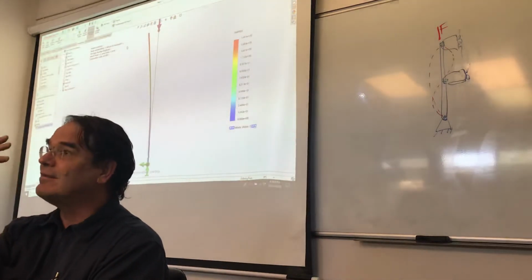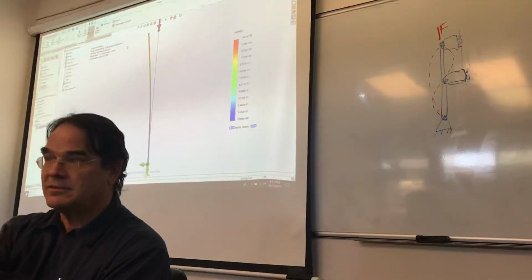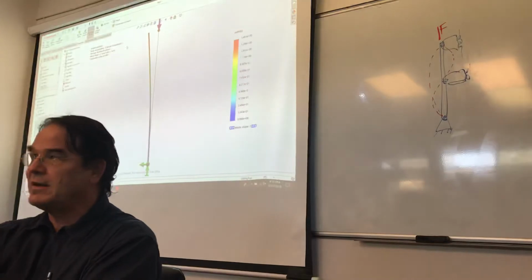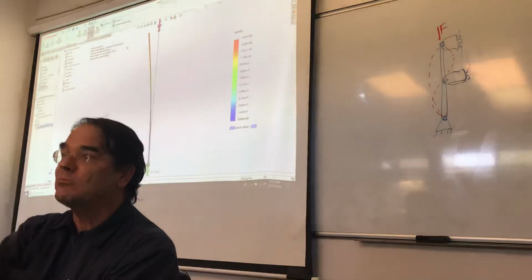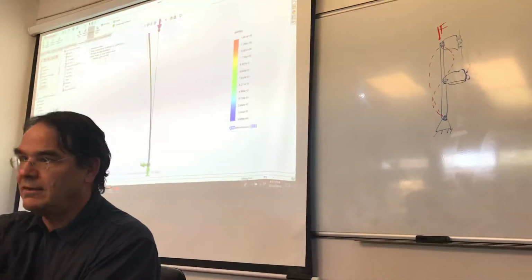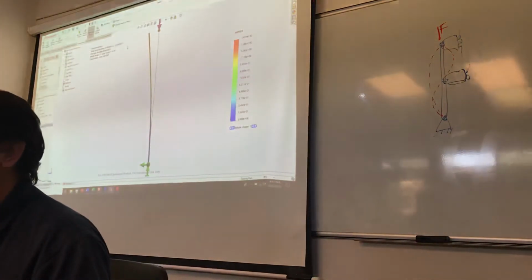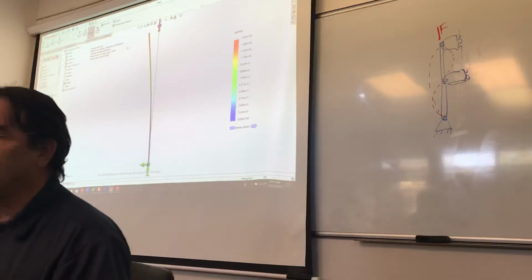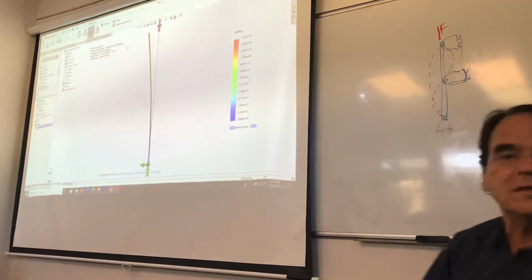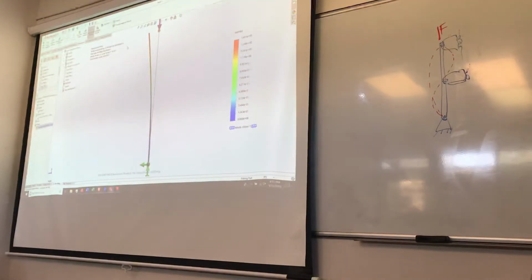But it takes a lot more to fail in one direction than the other. So it's buckling in the skinny direction at 11,000 pounds, or predicting that, and it's buckling in the wider direction at the 30,000 pounds, right? And we'll see that same behavior the rest of the way up, right?